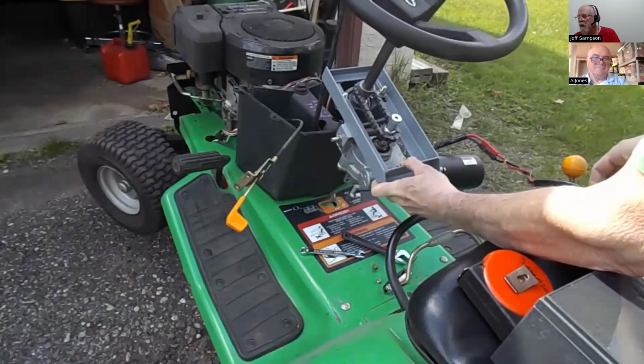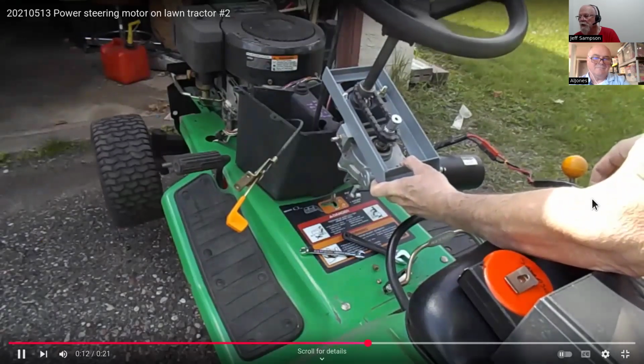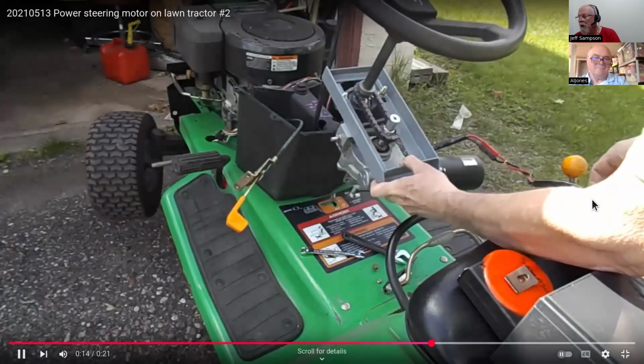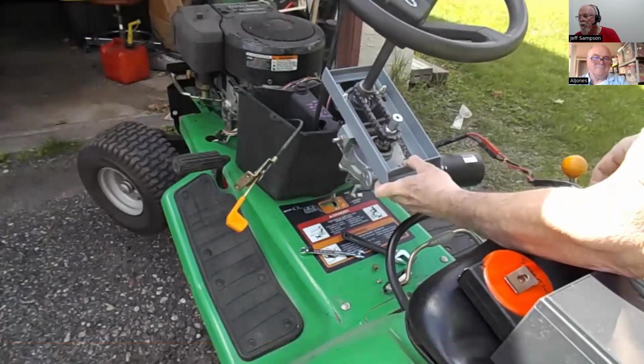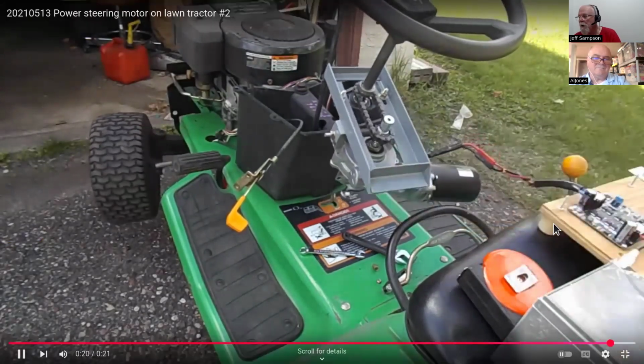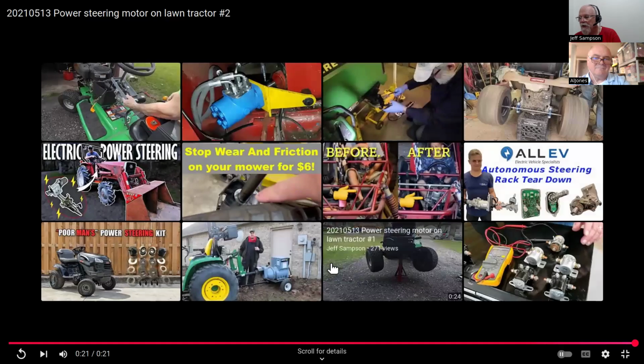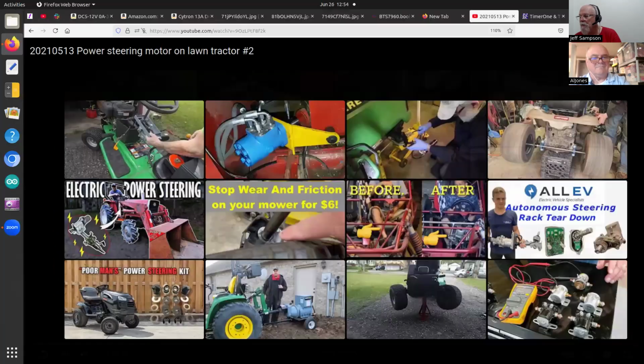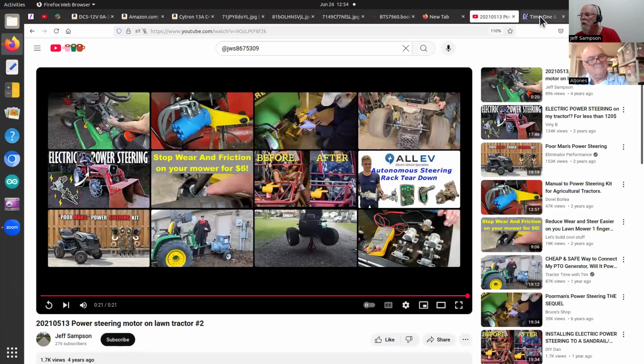And if I go look up the specs on that board, it might tell me what frequency it is, or I can put a scope on and I'd measure that. Which leads right into the fact I was going to talk about my scope. So anyway, that is the point. If you run your PWM frequency at a high enough frequency, your motors will not sing when you do that.